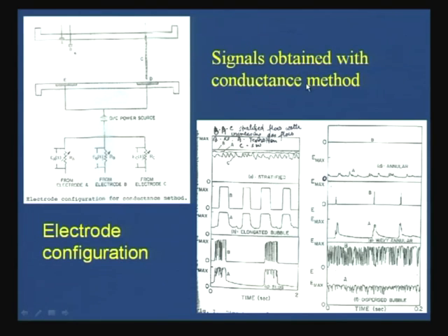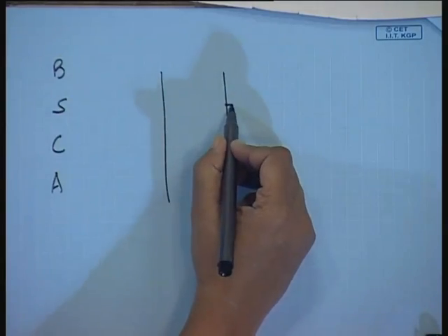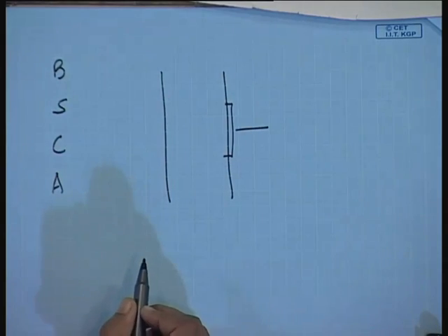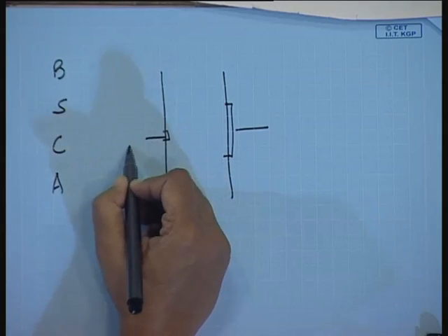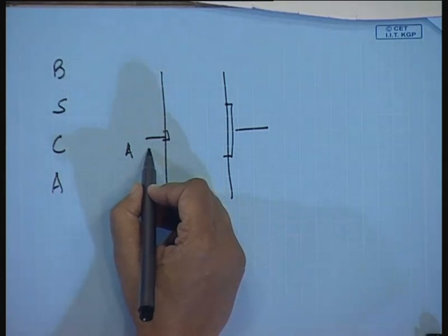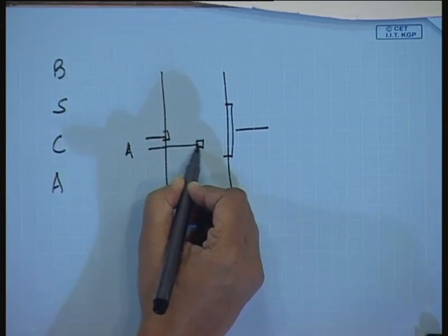So, this was the condition for the horizontal flow. Now, if we take vertical flow, definitely the situation is much simpler. Why? Because the number of flow patterns that we have to distinguish is much smaller in this case. We have bubbly flow, slug, churn, and annular. So, instead of the 5 probe system we can have one wall mounted electrode here, one small electrode which is probe A that I have mentioned, and maybe one probe B here.